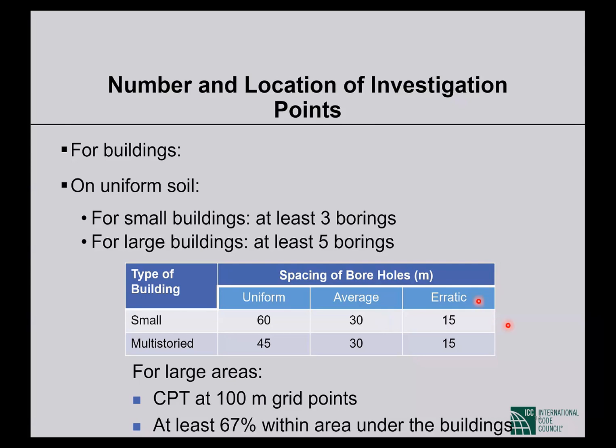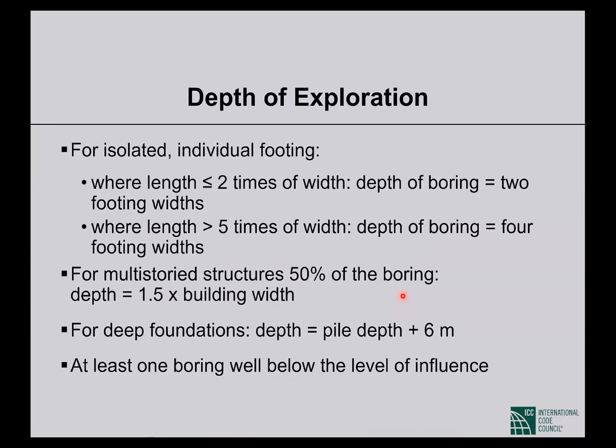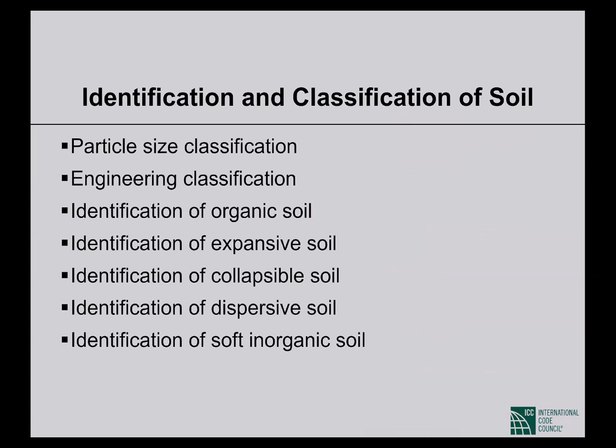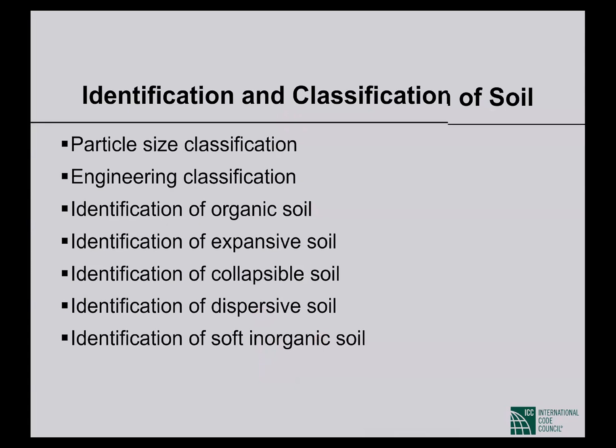So I would prefer to skip these slides, but I just want to give the information on how many boreholes should be done at a specific site. You can get some idea, guidelines from the code, things like that. And the minimum dimension of footings. Classification and identification of soil, information regarding these things are there.